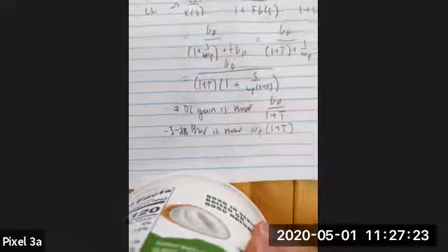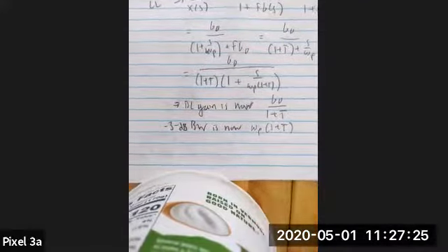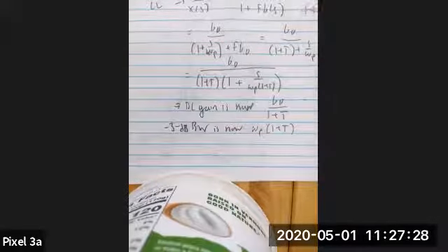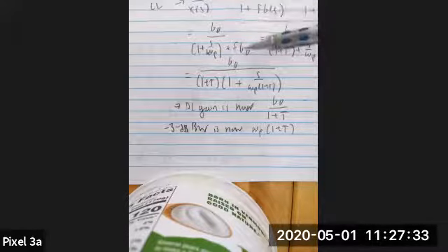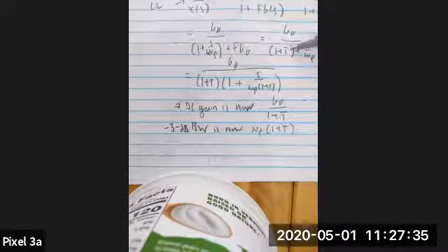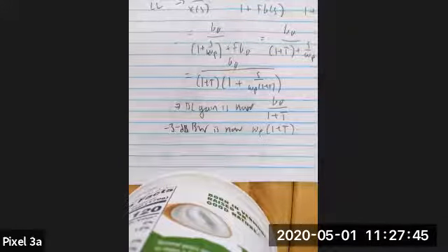How'd you turn s over omega p into T? Where did I do that? Can you go up to the? I just rearranged. So right there, you can see it. You go g naught over 1 plus s over omega p plus f. Oh, wait. So this f times g naught becomes the T over here, if that's what you're asking about. And the s just moves to the end. Oh, and then I factored out 1 plus T. Oh, okay. Fair enough.